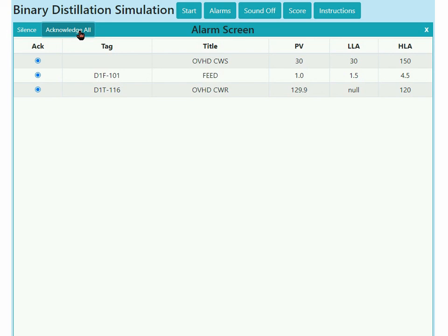Alarms do not clear unless they are acknowledged by the operator, so the operator always has a chance to observe the alarm. An operator could miss an alarm that cleared itself quickly, which might prevent identification of a problem. Close the alarm window by clicking the X in the upper right.